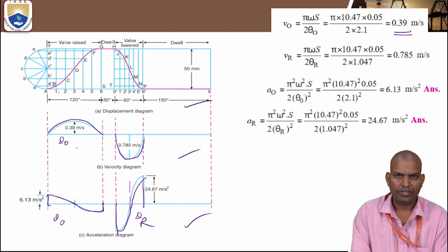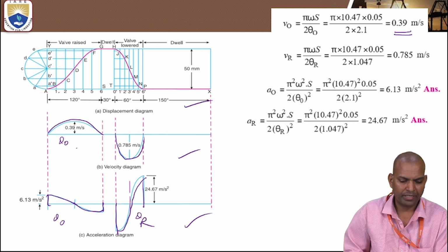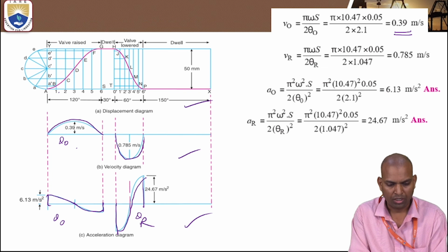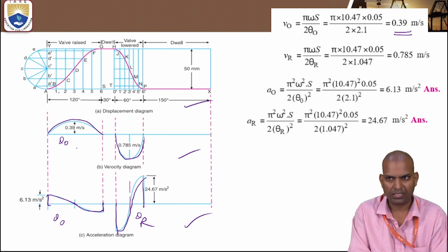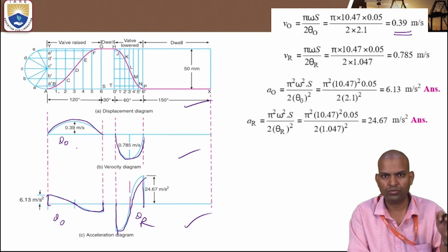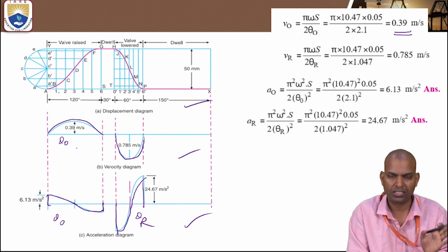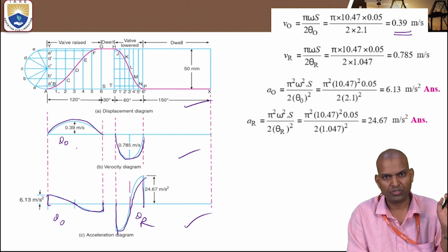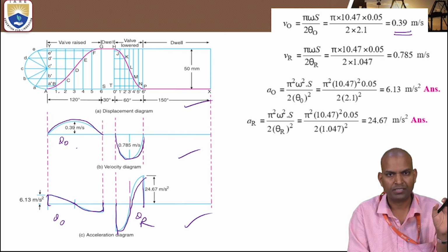Very important is that we have completed case 2. So we applied it for the offset circle. We should be very careful not to draw the radial lines. We have to use the tangential lines from the offset circle to the prime circle, passing through the divisions.